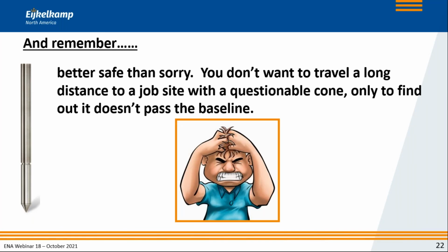Use those baseline readings. Start looking, not only the code requires that you save them anyhow, that you record them, but start looking at those things. Because if you start seeing that the baseline readings start to drift, that the baseline reading before you do the cone testing, before you do the cone sounding, which is allowed to be more than 5% different from the calibrated values. If you start seeing that they first differ 1%, and then a month later it's 2%, and then 3%, and they slowly creep up, then you have an indication, guys, something is not kosher.